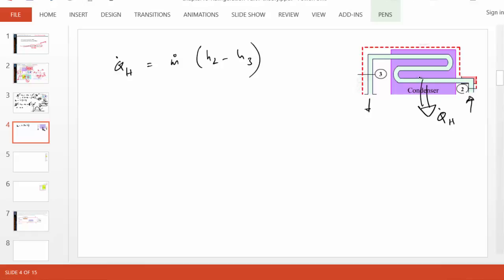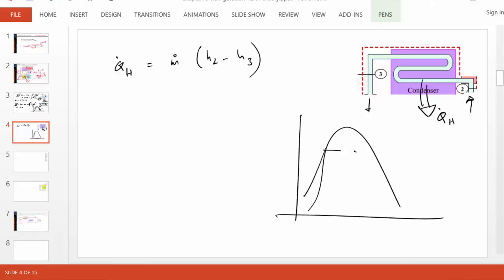And when the fluid is free to move, it doesn't affect the pressure at all. Because of friction, pressure may actually drop slightly, but we'll neglect that in an ideal condenser. In a condenser, essentially it's the opposite of boiling. If I have a state 2 here, pressure remains constant along this constant pressure line, and at the exit of the condenser, it's always assumed that I have a saturated fluid. In other words, this is my F state.